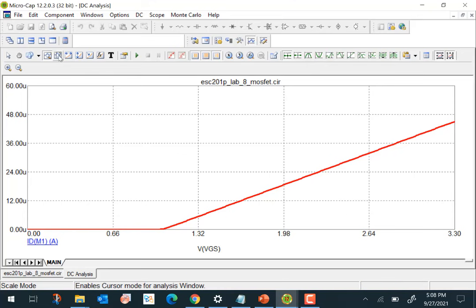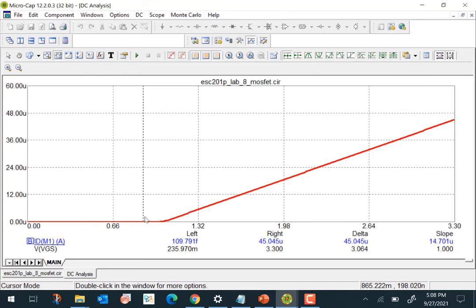And this is where the threshold voltage is, right here at this particular point. Note that it is 1 volt here. Threshold voltage basically means that the transistor begins to carry significant current once the gate to source voltage crosses the threshold voltage. Note that although it appears as if the current is 0 or negligible here, the current is not really 0.